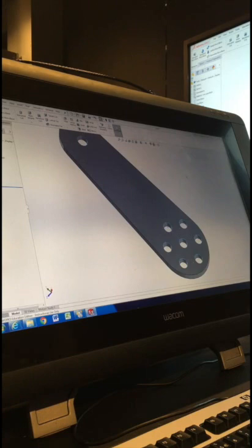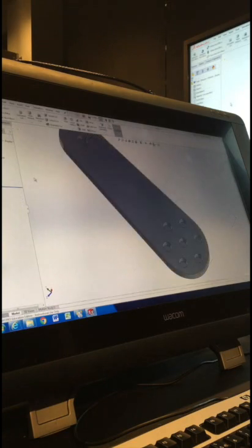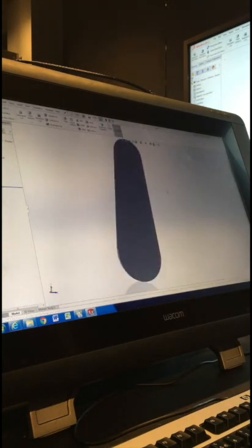All right, I'm just going to finish off this part. One last thing to show you guys, and then we'll move on to the next one. If you're still going on this part, that's fine. We've got plenty of time, and I'll come back and help you out. So I just showed you how that cut works. We did the extrude 5 millimeters, then we cut 5 millimeters. What happens if the thickness of the extrude changes? So I'm going to click Edit Boss Extrude, and I'm going to change it from 5 to 6. Now my cut doesn't go all the way through anymore.